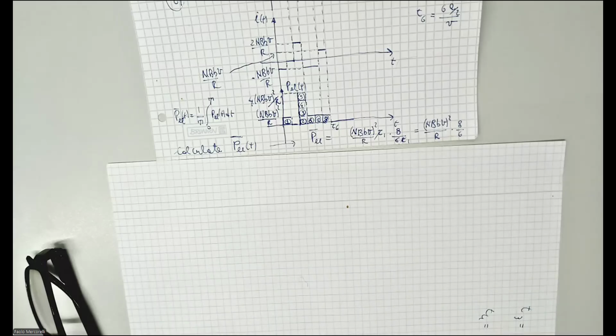To consider the temperature, I don't have time to tell you about that. But in some data sheets of the motors, of the actuators, we have exactly this table. From this mean value of power, we have this temperature. And then in accordance with our stress, we have to consider how to dissipate this thermal energy, which is reflected by the temperature.